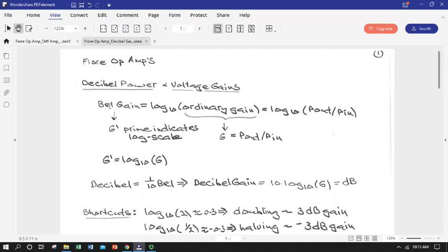So what's the definition of decibel power? And we'll start with power because that's really the reference, and it's why I started with the example of the power of a sound compression wave and perception in the human ear. When you hear decibel, think power. Unless otherwise noted, decibels always refer to a ratio in some kind of power. And if we use it for voltage or current, for instance, we're going to use the same power expression and then literally insert Joule's law, P equals IV, or P equals V squared over R,